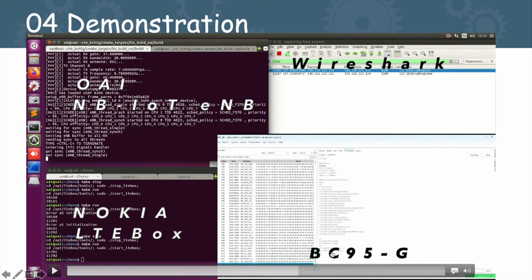Why should we lock the frequency here? It's just to reduce the time for the UE to connect to the base station. After locking the frequency, we do the attach procedure to let the UE know it should do the attach procedure now.